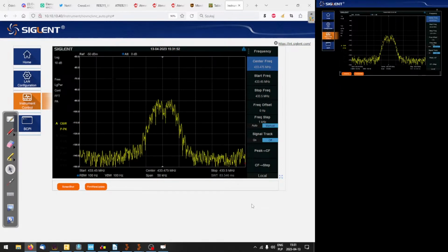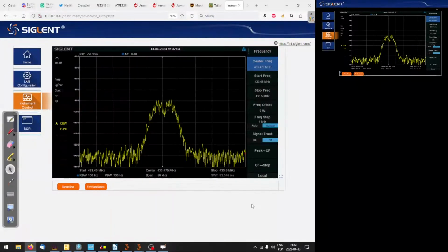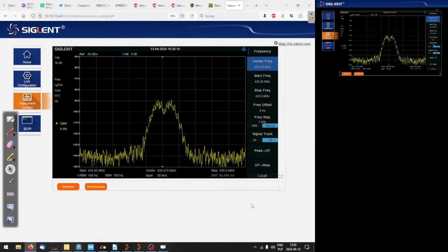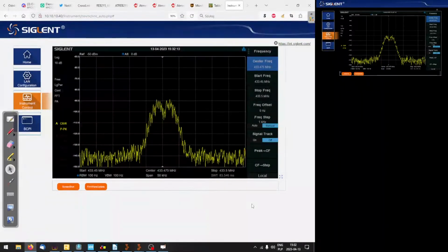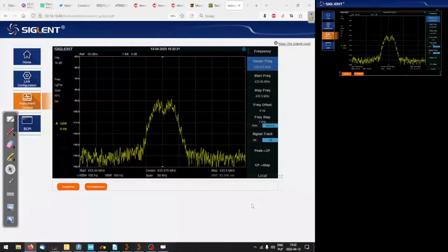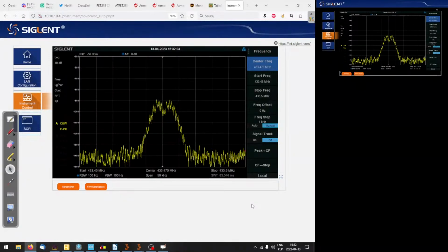Now let's actually confirm that the CTCSS is enabled in that radio. That's somewhere in the menu, R-CTCS. That's the menu entry in the Baofeng UV-82, the one I'm holding in my hand right now. So the beep is there, but the CTCSS decoder is off. So let's turn it on, and let's set it to 127.3 hertz. Yeah, the tone is still there.